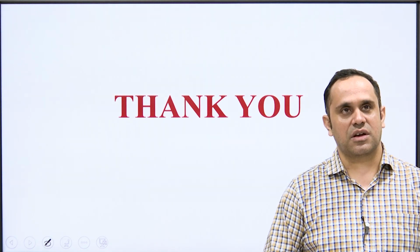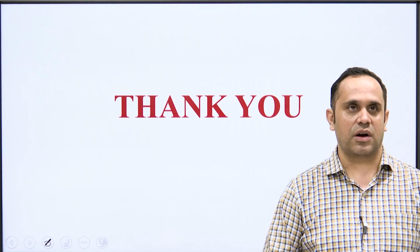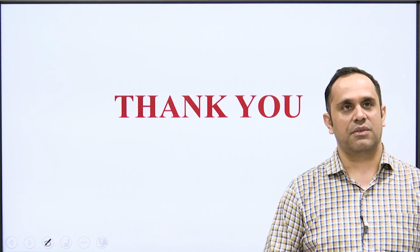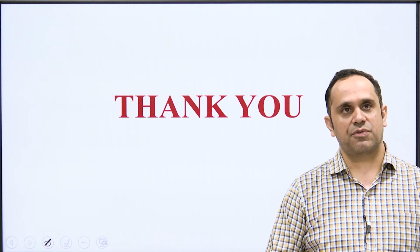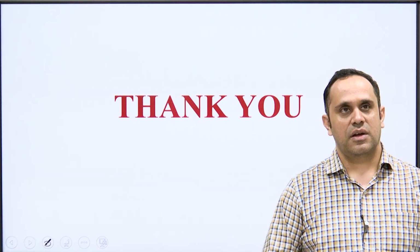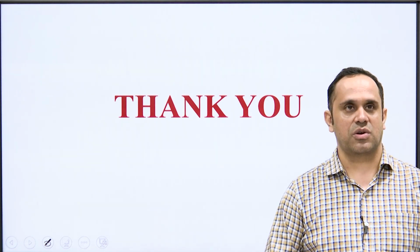Secondly, we have introduced the concept of faults, okay, and we have seen that most of the faults occur and are modeled at the logic level or the transistor level. And we have given you two types of common logical faults, one is stuck at fault, another is bridging fault. In the next lecture, we are going to continue our discussion on fault modeling.